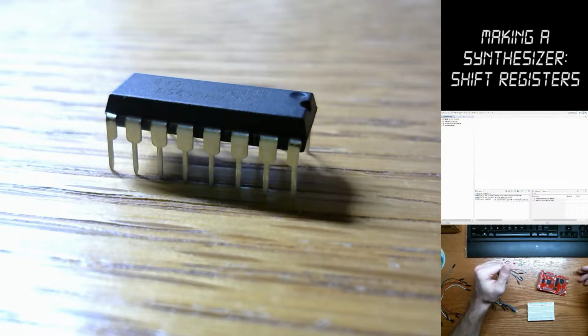In addition to that, you can output register values. By register values, I mean if it's an 8-bit register, which is what this one is, then each bit in those 8 bits will go to a corresponding pin, and they'll be high or low based on whether that position in the register has a 0 or a 1 stored, or a high voltage or low voltage stored.